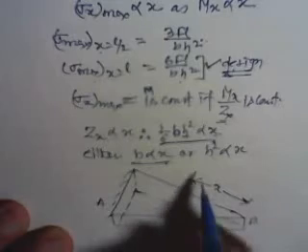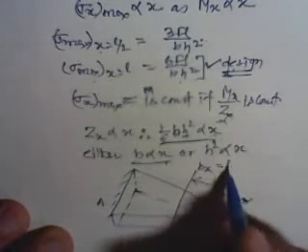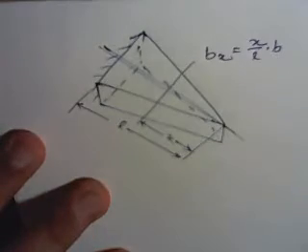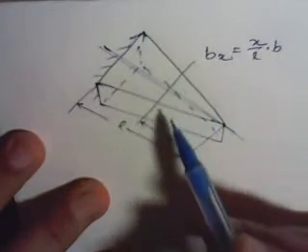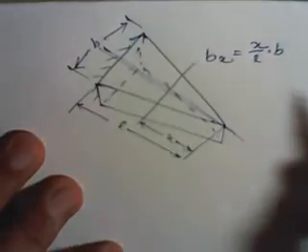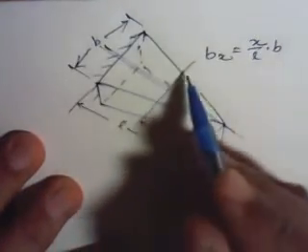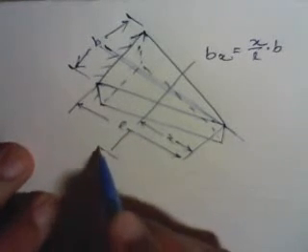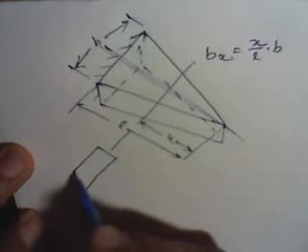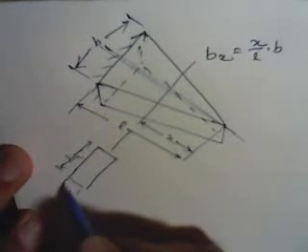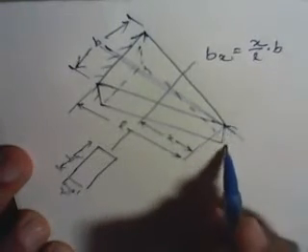Now this is A, this is point B. So here Bx is equal to B into x by L. So we finally got a cantilever of this size where the maximum width is B, and the cross section at any section, let us say this is the section, if I draw a cross section here, I will get this type of cross section where this value is Bx and this value is H. So this is what basically we got.